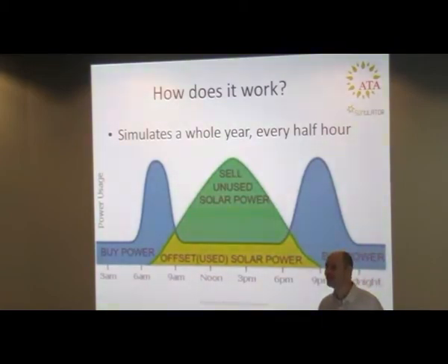Yeah, question at the back. Just to understand, so it takes a specific year's solar data? Yeah, good question. The data that we purchased from the Bureau of Meteorology goes back to the mid-90s. There were some gaps, but we had many years of data for each location. Obviously some years are sunnier than average and some years are cloudier than average, so you don't want to pick one that's too sunny or too cloudy. So what you do is you build up a typical meteorological year.